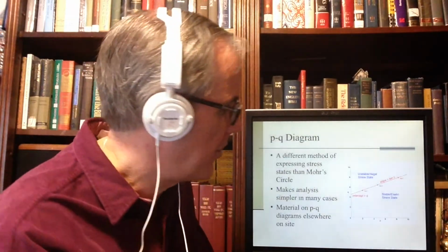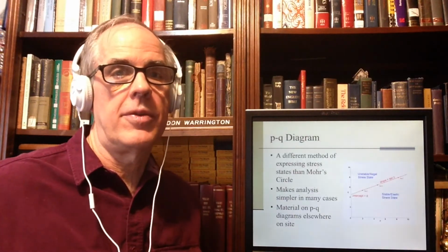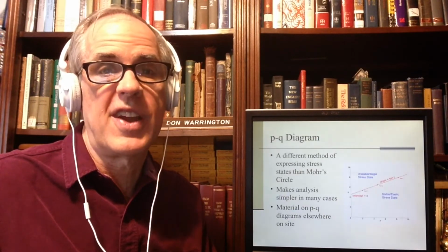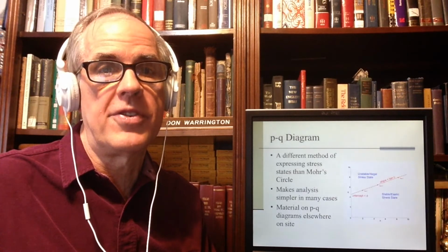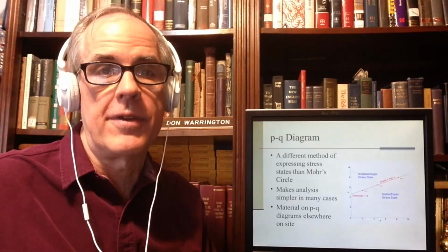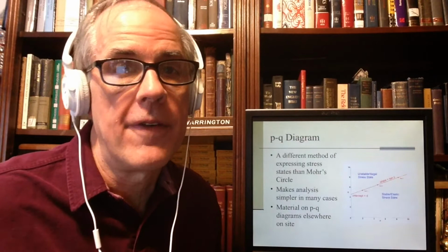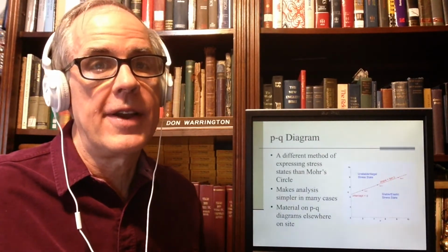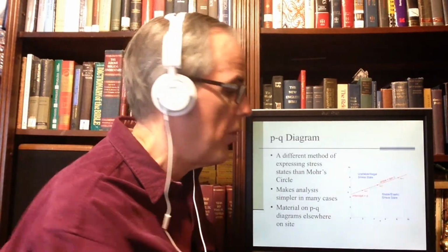And it's a lot easier to draw a line through points than it is to do it with tangent circles. Now you can do that with circles, especially if you've got more than 2 of them. If you have 3 of them, there's no necessity for those to line up perfectly. And if they don't, you can use the least squares method to figure it out. In fact, word to the wise, if you've got two specimens and you want to find out what the phi and C are, you can use this because these reduce to points.